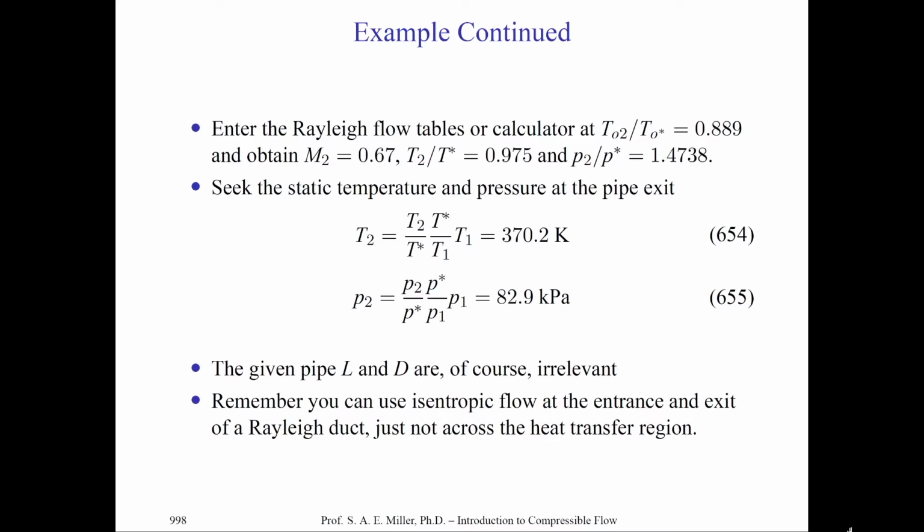So remember, you can always use isentropic flow equations at any particular point in the flow, because you are basically, figuratively, decelerating the flow to the stagnation conditions. This is also just like you would measure with a probe. We could indeed put a probe in a turbulent flow and find a total pressure and a static pressure, which, of course, vary with time.